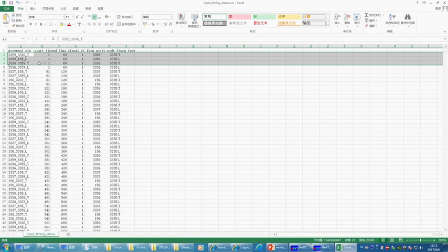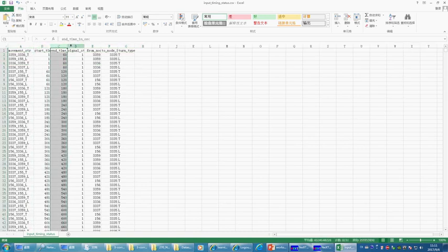through movement and left hand movement, how the capacity is being closed or opened for different vehicles. Again, we do not model the right hand movement capacity here because the right hand movement capacity is quite complicated and is a little bit beyond the reach of the mesoscopic simulation. So in this process, the user can check the open source code of the DTA Lite to see how this movement specific timing status is simulated, is generated, and for the advanced users, they can also change the source code in the NEXTA interface to do a more advanced adaptive signal control. Okay.